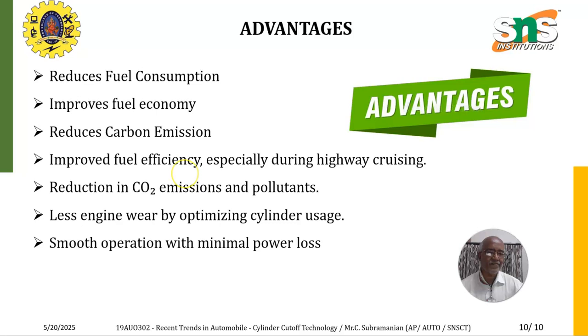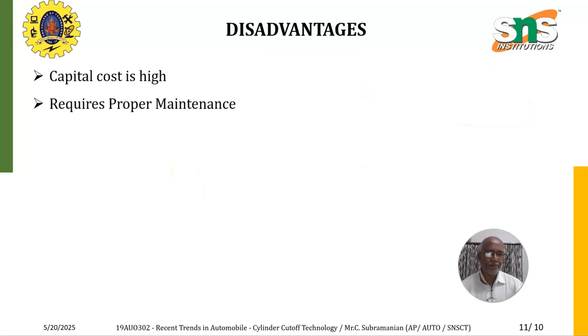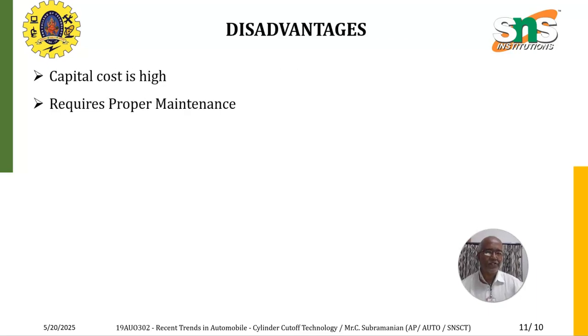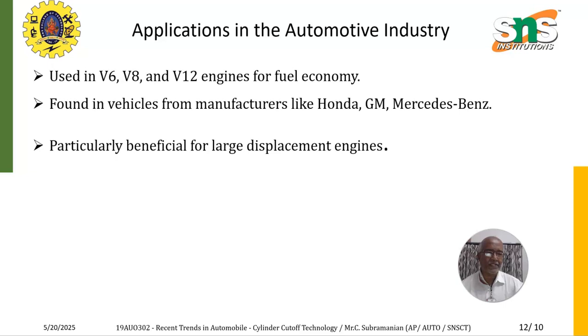Engine wear will be lesser, and there is smooth operation with minimum power losses. The main disadvantages are that the capital cost will be higher and it requires proper maintenance. Finally, we come to the applications where this cylinder technology is applied presently. It is used in V6, V8 and V12 engines. Some manufacturers like Honda, GM, and Mercedes-Benz are also using cylinder cutoff technology.